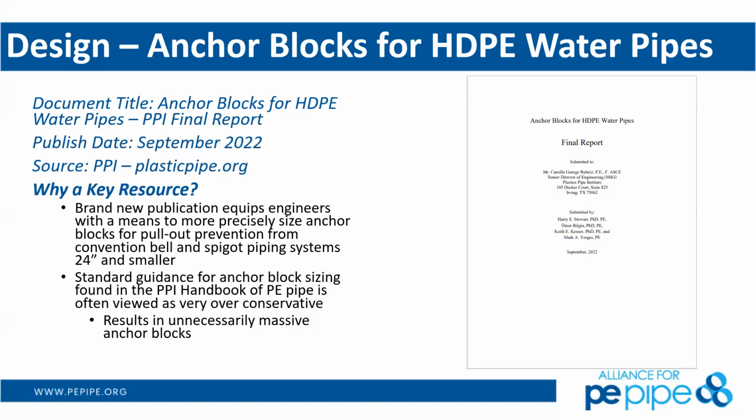That viscoelastic behavior that I had mentioned is also important in attenuating pressure surges in some places. So when we have water hammer coming through a pipe, essentially water hammer is a change in velocity of the flow material within the pipe. That translates directly to a change in pressure in the pipe. We look for thrust restraint along that water hammer when we have a change in direction for the pipe, or we're connecting to a valve or something of that nature.